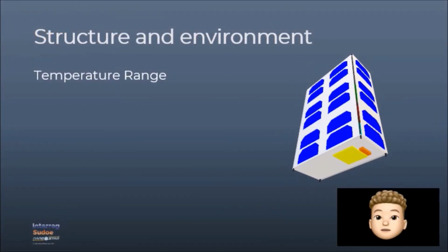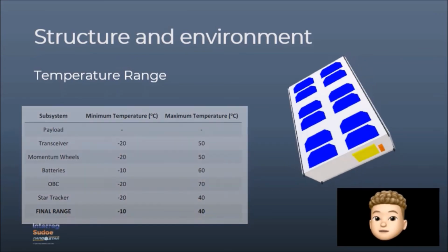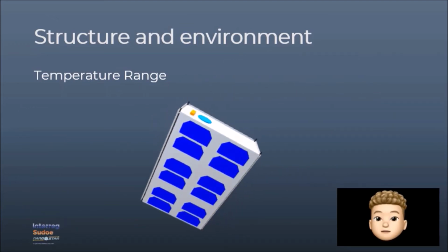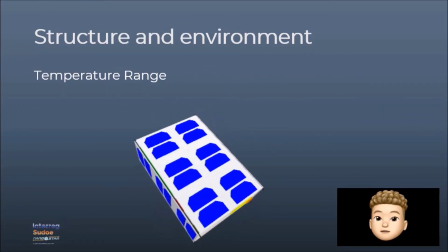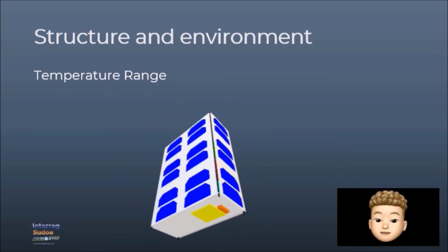In order to carry out the thermal control, heat flags must be analyzed. The satellite must remain at all times in a specific temperature range. This range was extracted from the ranges of all the subsystems involved. According to power needs, lateral faces were covered by solar panels. As the nominal operation of the satellite is without eclipses, the other two have been decided to be painted in white for lowering the maximum temperature at sunlight.